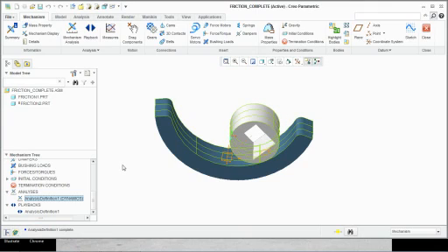It doesn't make many circles. So liftoff enables the separation between the two cam surfaces, and the coefficient of restitution tells you how quickly this motion is going to die, because it's all moving because of gravity. And friction enables you to slow down the motion. The higher the friction, the faster it dies down. So you can use a combination of both of them to get a desired result.